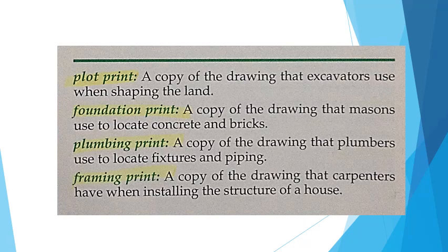Otherwise, the hole will need to be drilled after the concrete sets. Any cables that will be located under a driveway should pass through conduit. The driveway will not need to be removed if the cables are replaced.